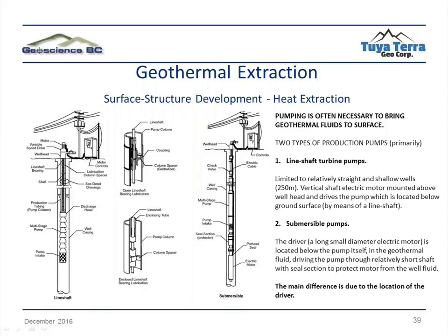Downhole pumps come in basically two varieties. One is called line shaft pumps, and the other is submersible pumps. What you have to remember in the choice of the pump is that the diameter of your well is important, and how much fluid you can draw out of that well with your pump.